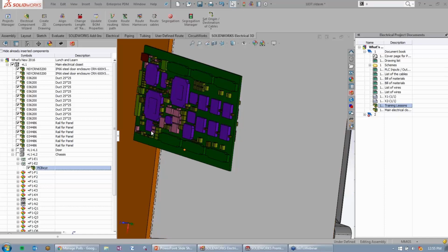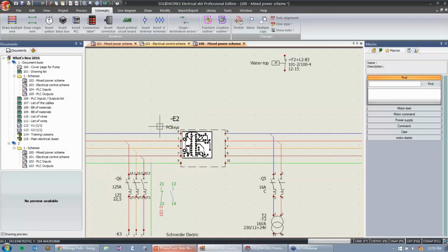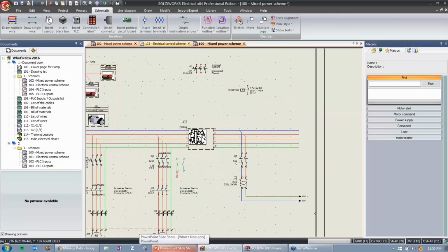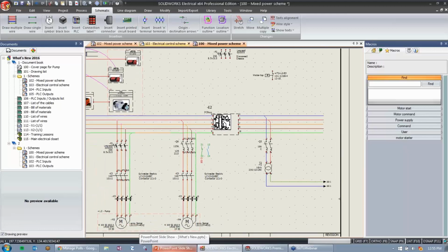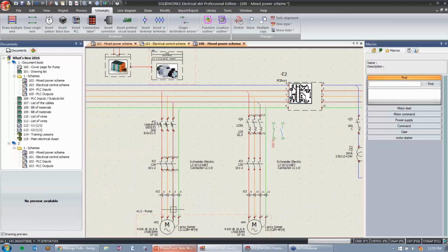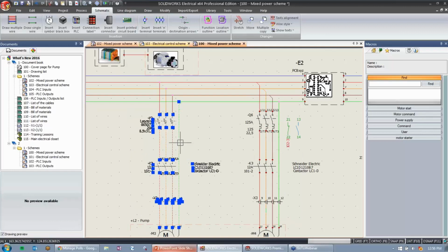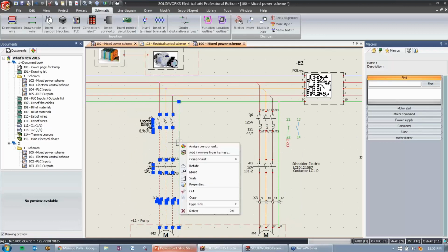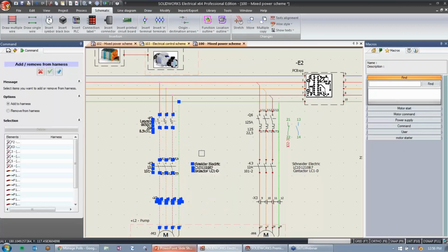All right. Is it possible to create routing for automobile harnesses? Yep. So we can create a harness inside the schematic tool. As we have our wires documented or our cables documented, the ability to create a harness requires just selecting the items and wires that you want. So if I want to grab everything between my fuse and my terminals, I can highlight those, right-click, and say Add or Remove to Harness.